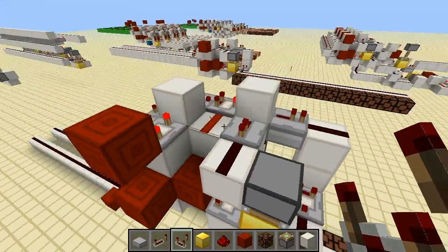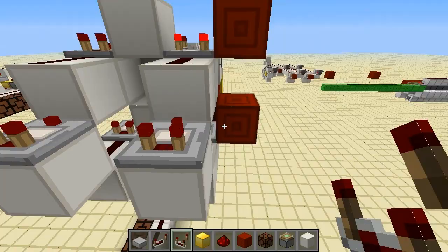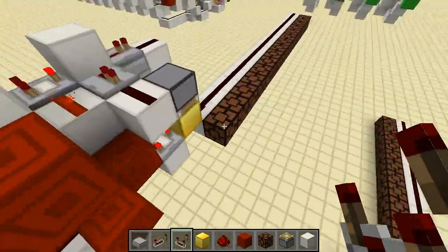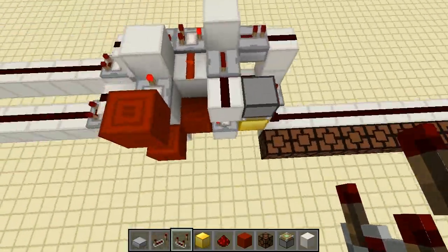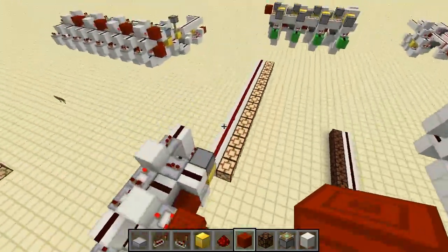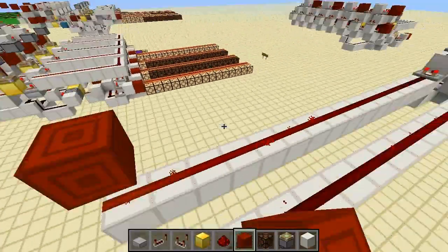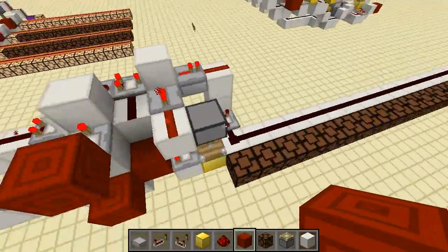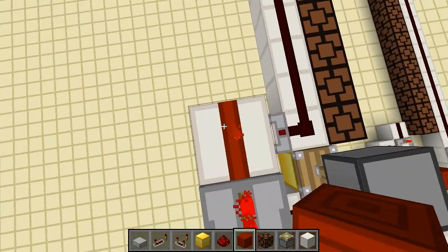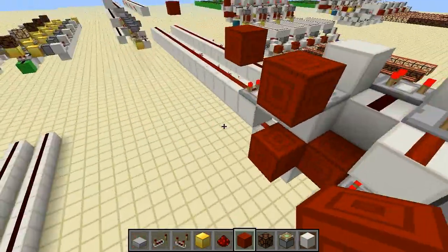This signal will match the sum of these two. Now we have one set up over here already with inputs and outputs. It's like Art Attack, isn't it? Or Blue Peter, maybe. So, if we input 15 and 1, we get an output of 15. And then if we increase this by 1, so we're getting 16, we get an output of 0 with a carry. And the carry to the next digit is worth 1 in the next digit, which is worth 16 in this digit. So that is a total of 16.